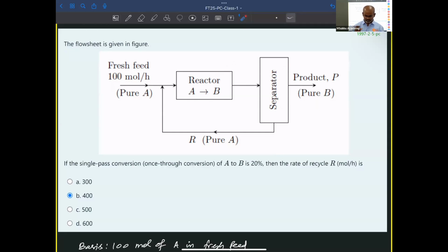Okay, recycle, of course, we cannot waste the reactant. So in that way also you have to recycle that. Since you are handling more content, for 100 moles, here we need to have 500 moles of A available. That we are calculating, of course. Only then, out of that 500 moles, 20% is utilized for these reactions, and the balance 400 will be recycled.